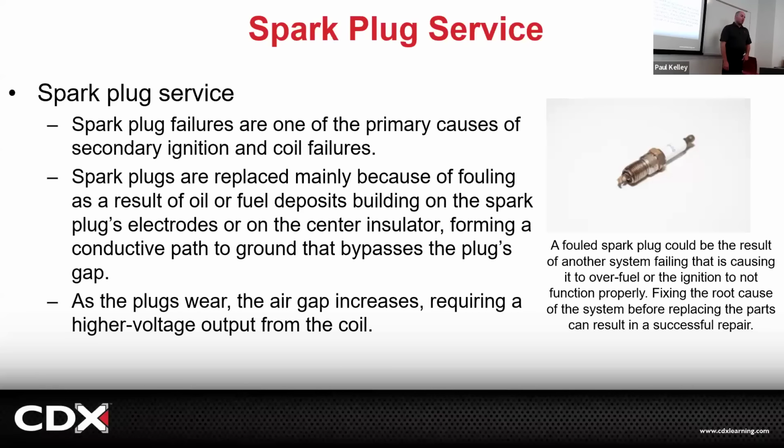What about spark plugs? Ooh, well, they're one of the primary causes of failure. I would say with a modern system with those really high quality $15 spark plugs, they're probably not the most common, but they're still one of the most. Now, why do we replace them? Well, a lot of times because of fouling. So what is fouling? Well, fouling is like a deposit. It could be oil fouling. It could be fuel. There's even coolant technically can do it.